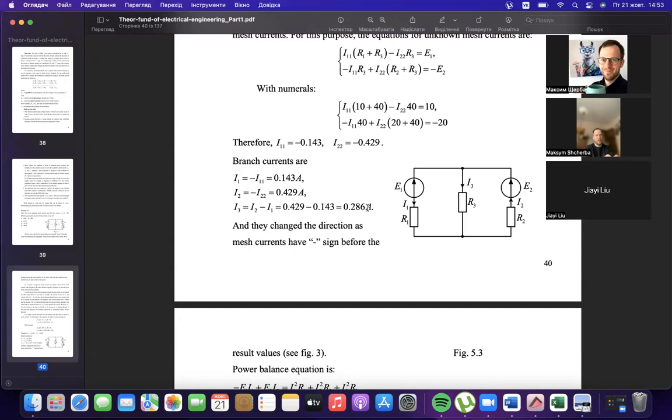And we could check the Kirchhoff law to check if we found this solution correctly. The sum of all 3 currents should equal 0, or, depending on the direction, we have inflow current I2 and outflow currents I1 and I3. That means if we add I1 plus I3, we should get current I2.